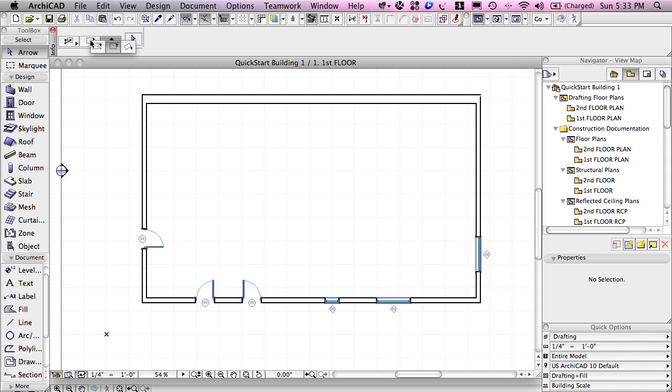Now in addition, you can also change your marquee selection to an irregular shape. So we had it in a rectangle. If I choose an irregular or polygon shape, then perhaps I might be able to draw a box of some arbitrary shape, and I can click any point twice to finish it, or I can go back to the first point.